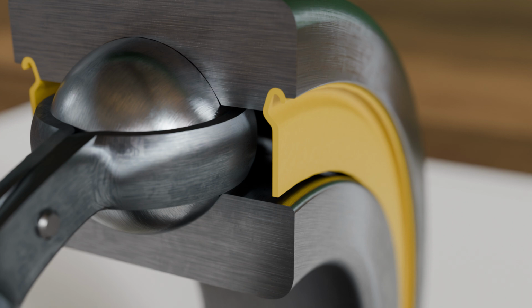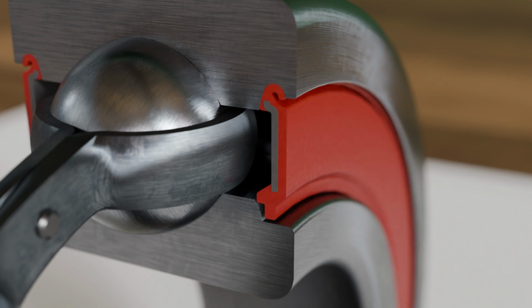For improved sealing, special sealing shields made of NBR are used. They have a significantly smaller gap to the inner ring, enabling a more effective sealing function, especially against moisture and fine contaminants. However, contact may occur. Therefore, these seals are classified as low-friction contact seals.